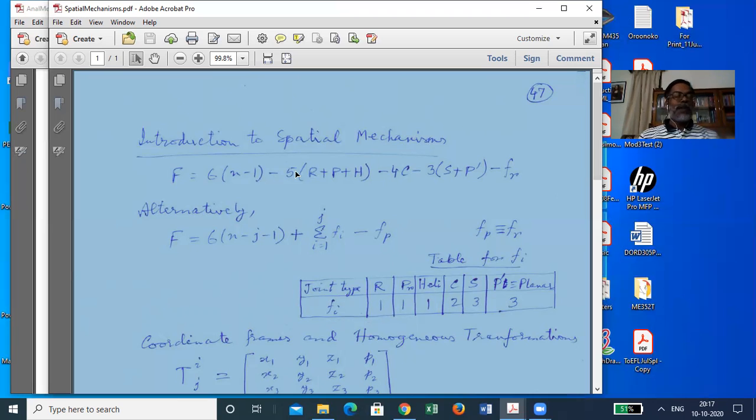So in the case of planar mechanisms, all the freedoms that we have been talking about for the last 14, 15 lectures are all very special, because in the spatial embedding, all the revolute axes are parallel. And that is a very special condition. Under that only, we could use all the planar formulae. Okay, this is one thing. Now, a spatial mechanism with only 4 links, 4 revolute pairs, will not have any freedom. In fact, it will be not only a structure, but a statically indeterminate structure.